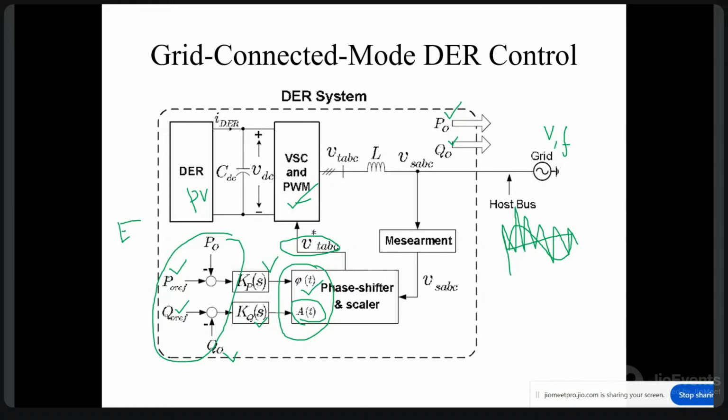Yes, anybody? Sir, harmonics. No, sir, no. See, harmonics can be eliminated by having a proper modulation technique. Sir, the source voltage may decrease. Sir, which voltage? The source voltage will vary according to the load. As the load varies, the source voltage also varies. Not necessarily, sir, because generally we have a DC bus capacitor which stabilizes the source voltage.